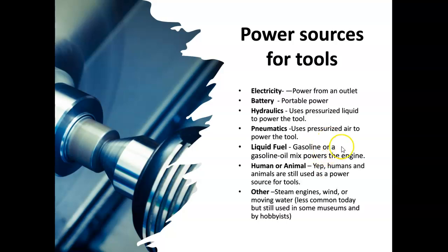So I do want to mention, going back to hydraulics here for just a minute. We typically talk about this being a fluid. It is generally hydraulic oil. There are dangers to using hydraulic oils. So we could also be using water, although oftentimes there's rust issues. So generally it is an oil.